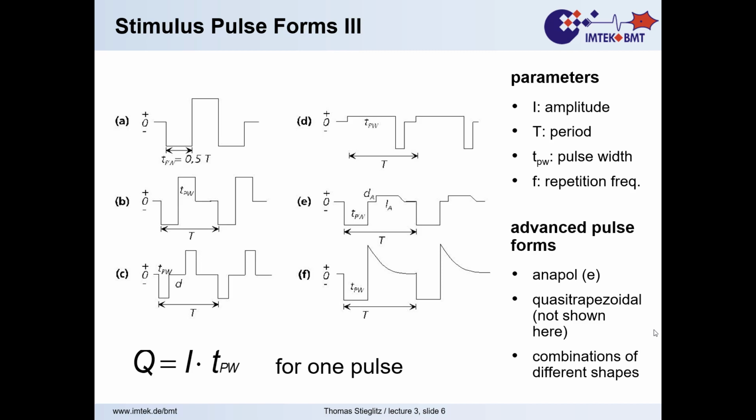If you do that in extreme cases, for example, fixing the second pulse at 20 microamperes or 40 microamperes, and saying, well, my first pulse should have a pulse width of 150 or 200 microseconds, which are typical numbers for those pulses, and I want to have a repetition frequency of 20 or 40 hertz, then your amplitude of the first pulse is limited by the time period.